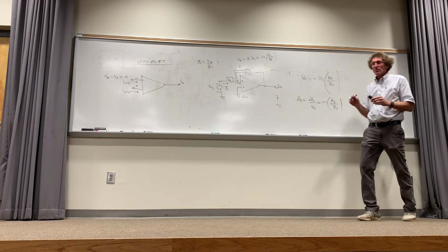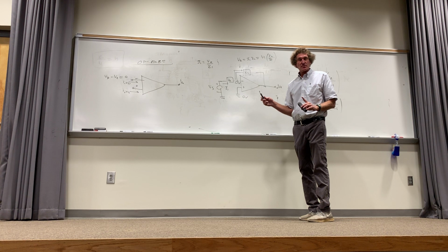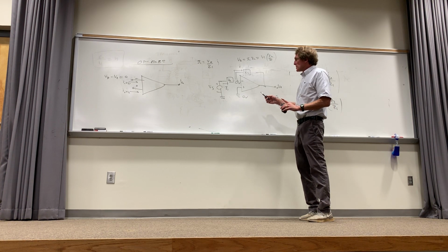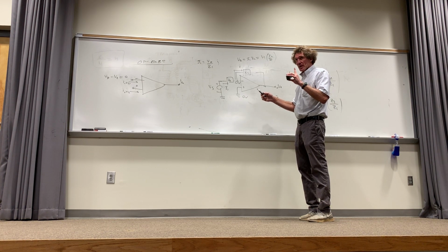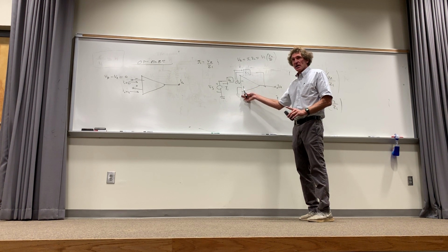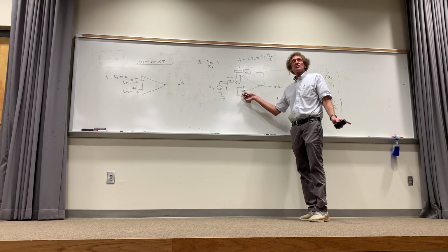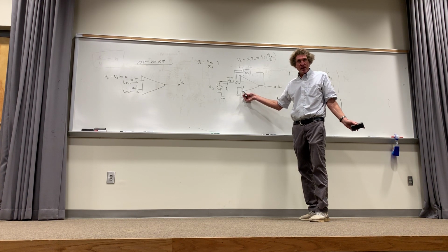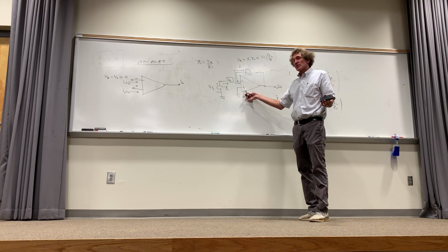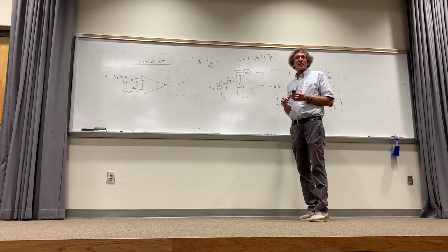Now, the final thing I want to say is, I'm going to give you some operational amplifier problems to do. But what I'd like you to do when you're doing them is remember the law: no current into the differential terminals. So you're always trying to get the voltage at one of these two terminals. That's the bottom line, usually a good starting point. Sometimes you can't. And then since no current goes into them, whatever voltage is on one side that causes a current, that current will always be shunted around it. Follow me, class? I'm going to give you some of them.